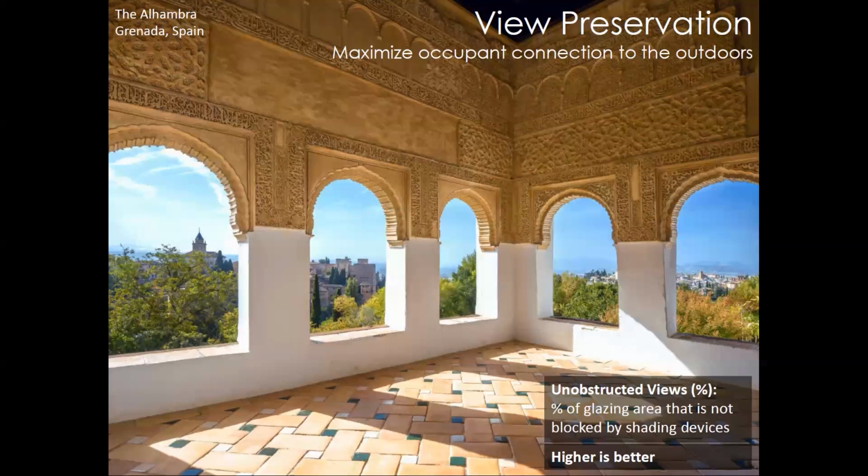Unobstructed views defines the percentage of window that is not blocked by a shading device, such as blinds, louvers, roller shades, etc. And for roller shades, this percentage is represented by the relative position of the shade hem bar in comparison to fully open, which is 100%, or fully closed, 0%. So for example, a shade deployed to 6 feet above a finished floor on a 10-foot tall curtain wall system has an unobstructed view of 60%.